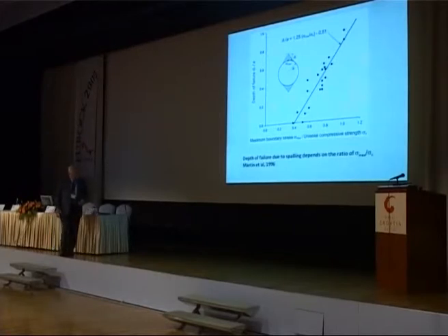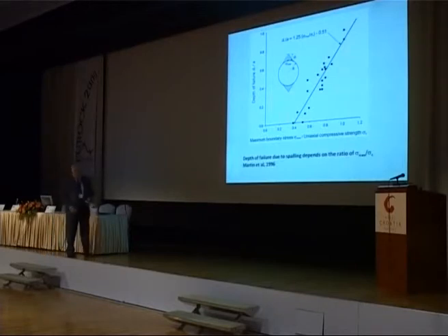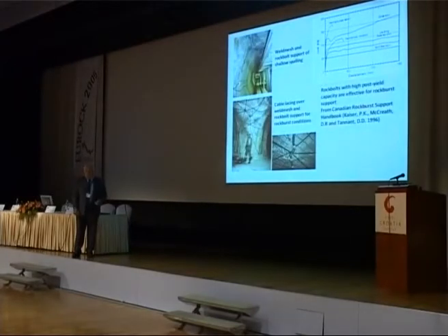What we do also know is that you cannot stop this failure. Once the rock is overstressed, it's going to fail. That's a given. But you can control the behavior of that rock relatively easily, because you don't need a lot of force in order to throttle the development of the spalling. So simple mesh and rock bolts tend to work pretty well for many spalling situations.